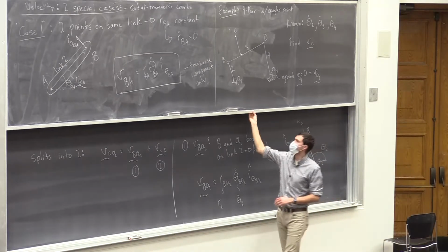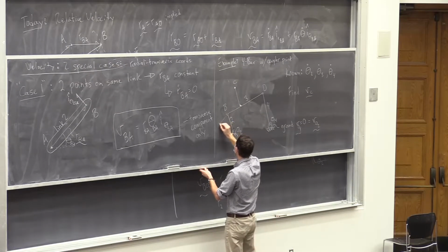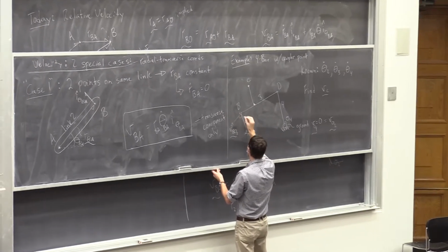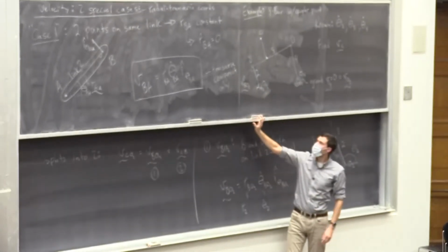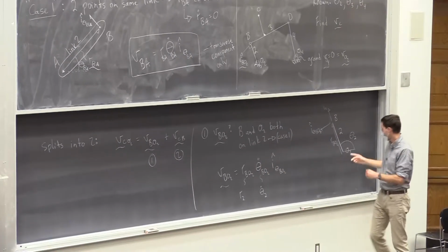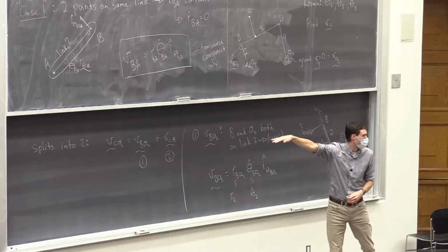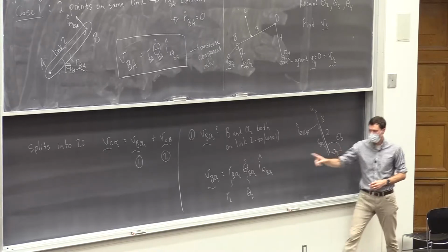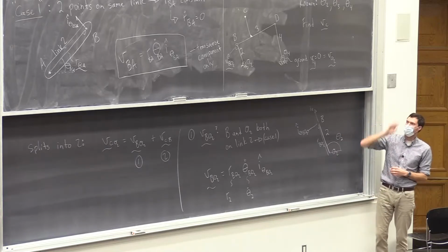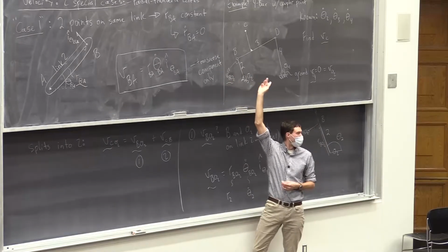Okay, I'm going to put it up on the original diagram here. So it's perpendicular to link 2. And if theta dot is positive, that means this angle is getting bigger. If theta dot is positive, the velocity will be down and to the left. If theta dot was negative in our equation, that means this angle theta 2 is getting smaller. That means the link's rotating clockwise. And this is still correct, but it's a negative sign on it. So it would point the other direction.